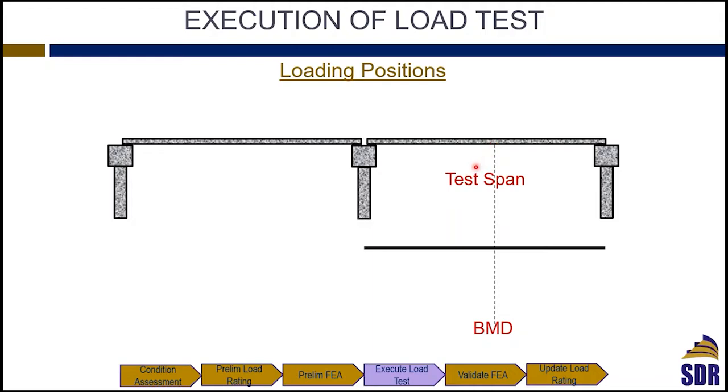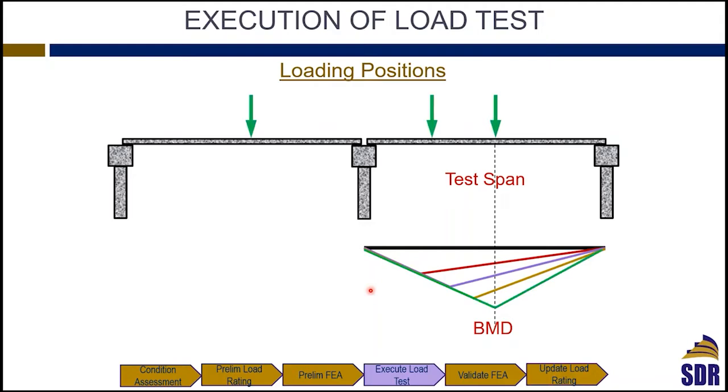You'd like to apply the load incrementally. But how could you apply the load incrementally? And we do this in a smart way. We start moving the load. So we start moving the truck on the span. You'll see your maximum moment is under the load. Once you start moving the truck in and getting closer to mid-span, you are increasing your mid-span moment, and you're increasing your moment under the load. Same thing, you keep moving the load until you move your load to mid-span, and this is what will get you the maximum mid-span moment.